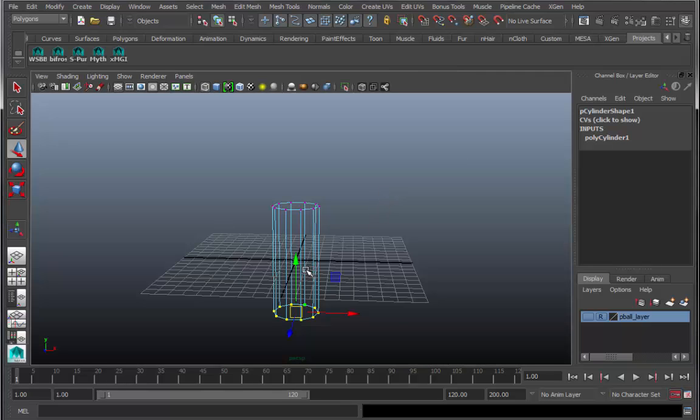Q is of course the selection, so that's sort of a QWERTY Western typewriter, upper left hand corner set of buttons. So what I'm going to do is hold down the X, and yes, I can do this in perspective view as well, because I live dangerously. Hold down the X because this will pop it onto the grid. I'm going to grab the arrowhead of this arrow, keeping it only in that axis. So when I click, I now snap it up to 0, 0, 0.